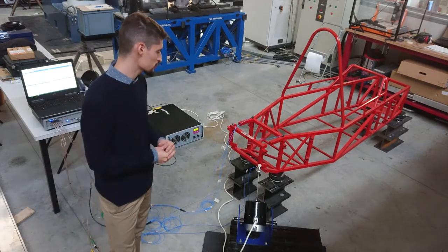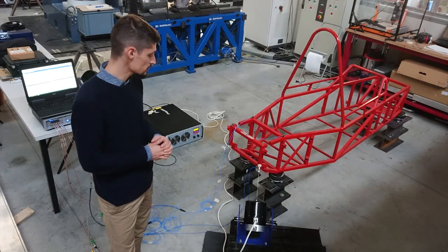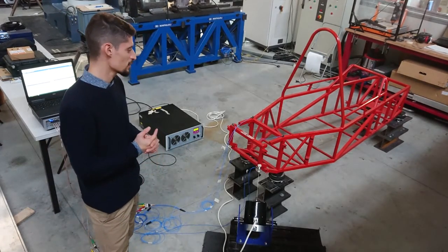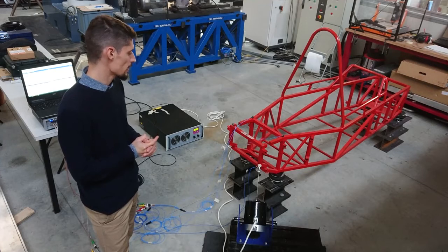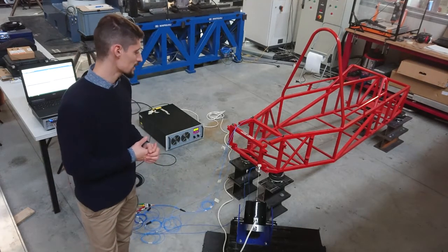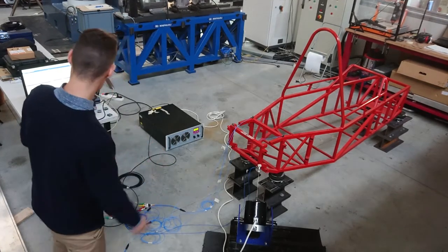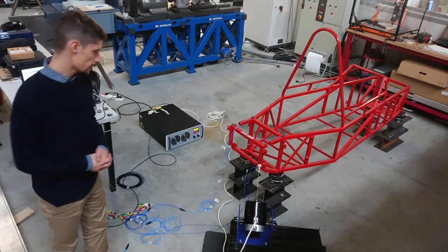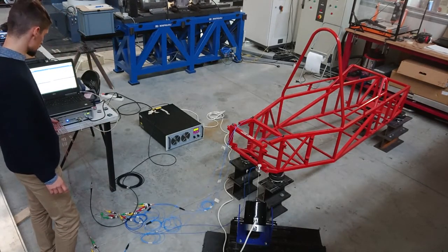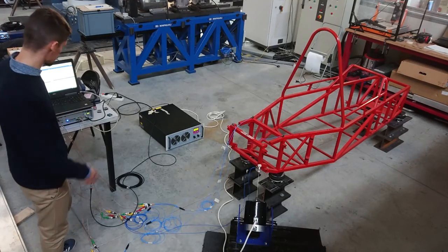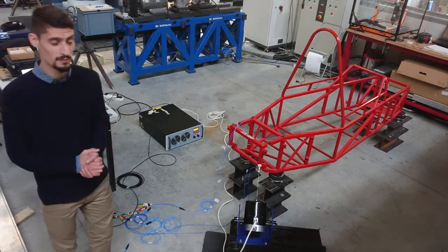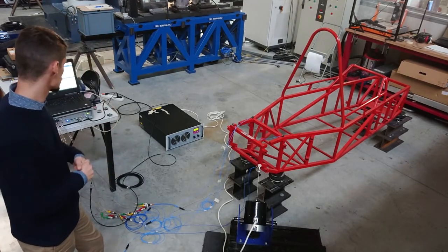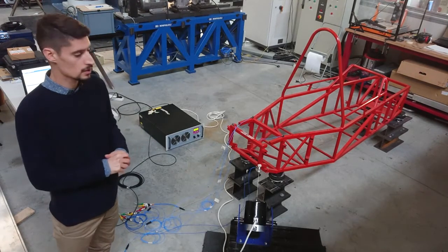Anyway, it's not so easy to have 21 accelerometers because just imagine that one 3-axial accelerometer costs more than 1,000 euro. Moreover, if you have 21 3-axial accelerometers, your SCADAS must be capable of acquiring more than 60 channels simultaneously. In this case, our SCADAS can do that because it can acquire 64 channels simultaneously, but this SCADAS is very expensive too. And we have other data acquisition hardware with 8 or 16 channels at most.